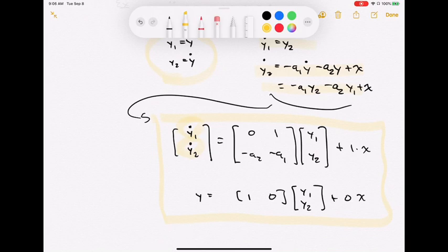And that state space representation, right, we had a second order system. So the big idea here was what? Take a second order system and represent it as a coupled set of first order equations. Second order system, I'm going to need two first order equations coupled together. And that's what this matrix representation does. It allows us to employ linear algebra in order to understand and design and work with these systems, which maybe for a second order system isn't all that big of a deal, but when you get to super high order systems, it is a big deal and it really helps out.